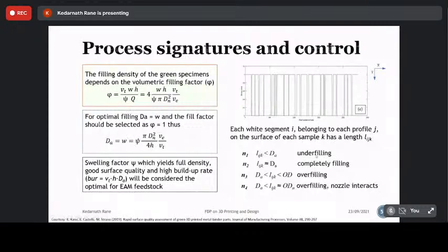We understood that there is underfilling, overfilling, and scratching of the nozzle with the material, where overfilling makes the nozzle interact with the depositor. If there is a lot of swelling of the deposited powder feedstock, there is a lower print height, then you have issues.